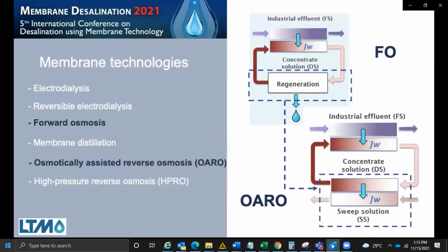On the one hand, as forward osmosis operates at low pressure, it results in fouling layers in the membranes that are less compact and easier to clean than in the case of reverse osmosis. This reduces the operating cost for scale control and extends the applicability of forward osmosis in ZLD systems to wastewater with high fouling potential, and it can be incorporated as an emerging technology in the development of ZLD systems.